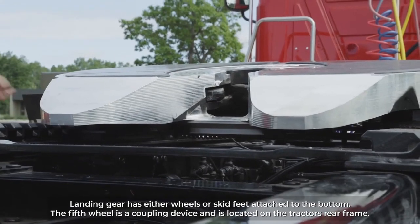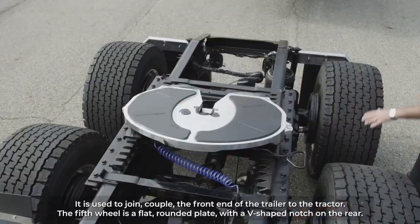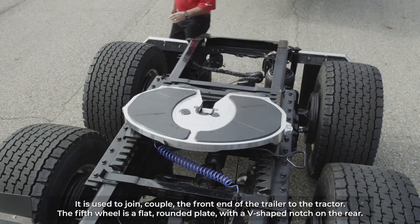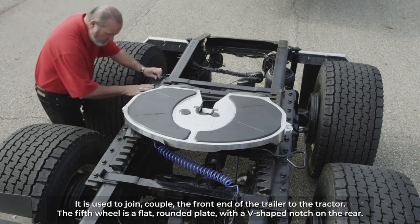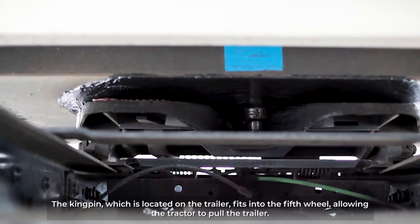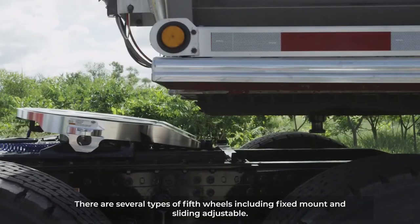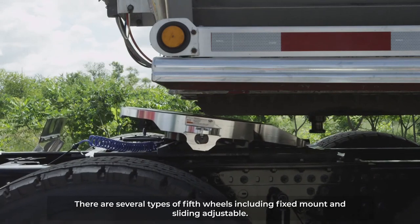The fifth wheel is a coupling device located on the tractor's rear frame. It is used to couple the front end of the trailer to the tractor. The fifth wheel is a flat, rounded plate with a V-shaped notch in the rear. The kingpin, which is located on the trailer, fits into the fifth wheel, allowing the tractor to pull the trailer. There are several types of fifth wheels, including fixed mount and sliding adjustable.